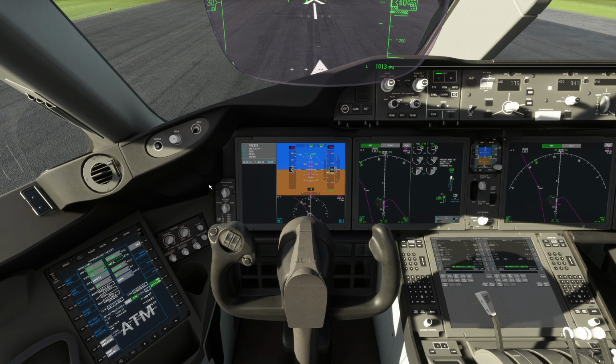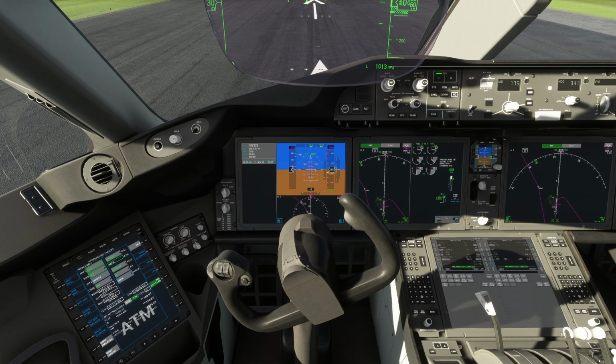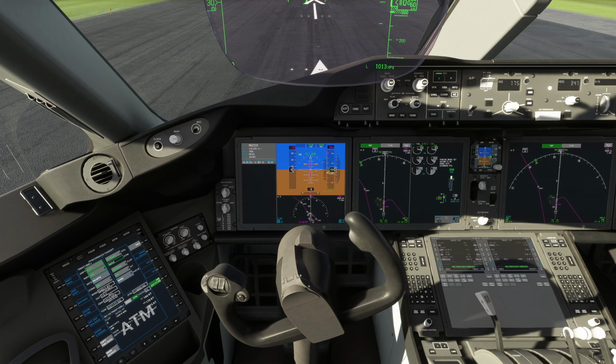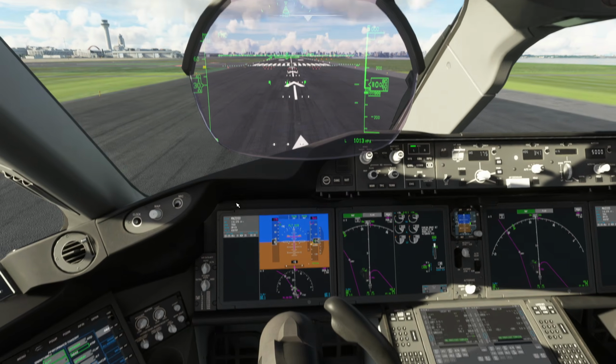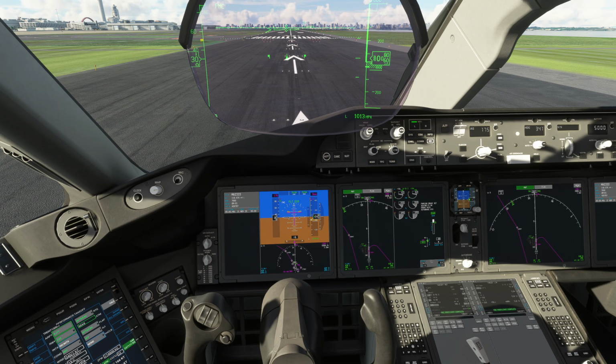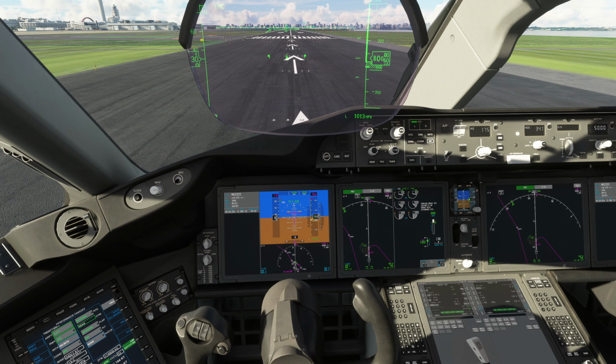Now that means that in a strong crosswind, you'll probably get towards the end of the runway, and at the rotate call, let's say the wind was from the left, so the airplane's trying to turn left, so it would have had right rudder in, and would also have had into-wind aileron. So you have something weird like that, sort of cross-controlled. What you're going to do is rotate the aircraft like normal, move that airplane symbol up to the toga reference line, so moving this airplane symbol here up to that dash line, which you can't quite see yet. And it's only when you're in the air you then relax all these controls and allow the airplane to weathercock into wind, and it will then point into wind.